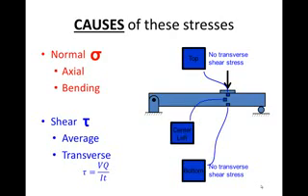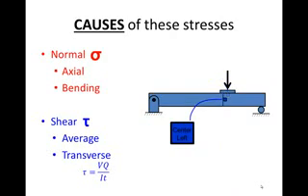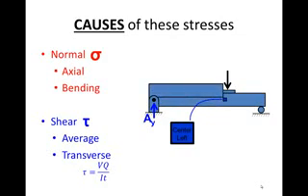But the center has the maximum amount of shear stress. We're going to compare the center fiber just left of the load with the center fiber just right of the load. First of all, let's look at the center element of metal just left of the load. The reaction force here at point A would try and shear the part of the beam upward like this. So the element would have a shear stress upward on the left side equal to VQ over IT.